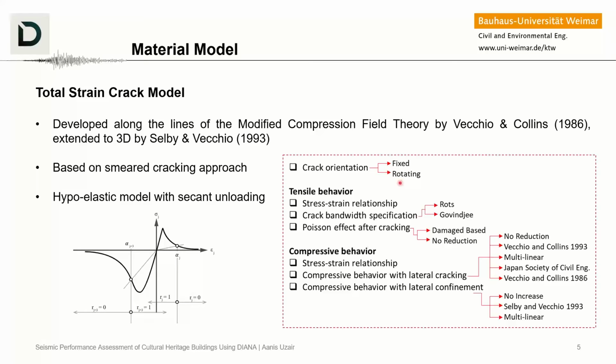And when the variety can be huge, then the uncertainty that arises from the choice of your material model also becomes extremely large. So the results for various assumptions can show large discrepancies. Smeared crack may give rise to locking, and the fixed smeared crack may produce overstiff behavior, while rotating smeared cracks do not. In this case, choosing what is right and what is wrong becomes very ambiguous and difficult. That's why we evaluate the structural system on the basis of the worst possible response.